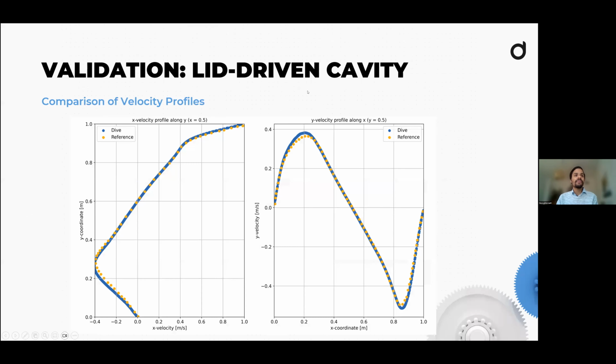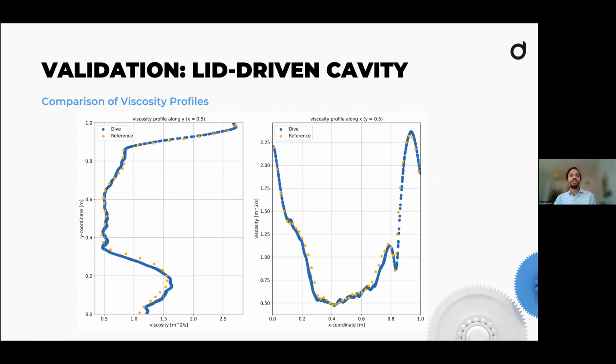And then we basically checked velocity profiles at certain reference positions, which is a very good benchmark that we also would recommend to any other person that is benchmarking non-Newtonian fluids in SPH or any CFD code actually. And we also compared it to viscosity profiles at the same locations, and we see a good match.